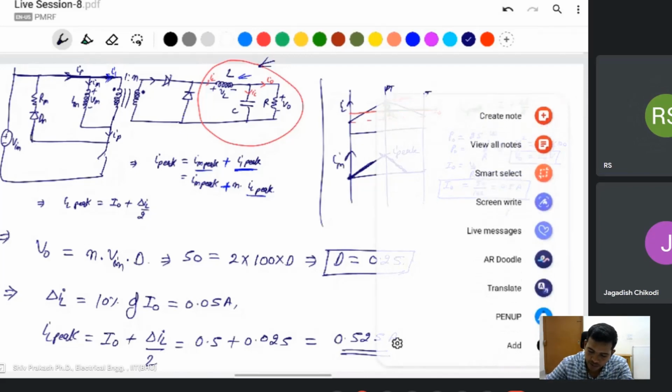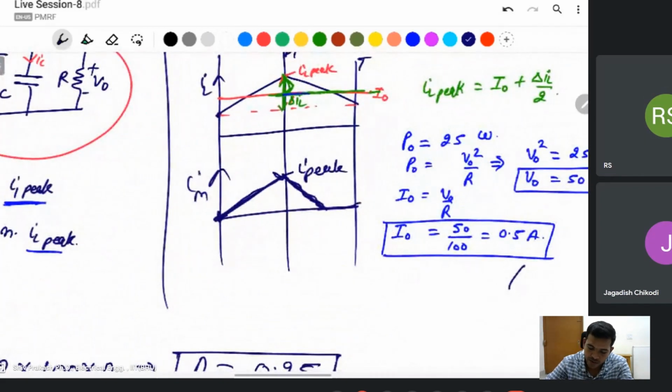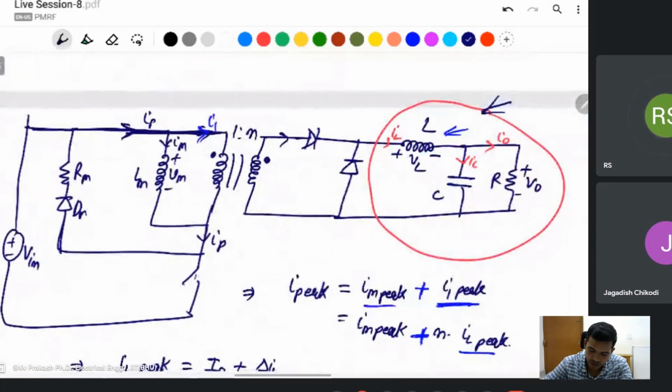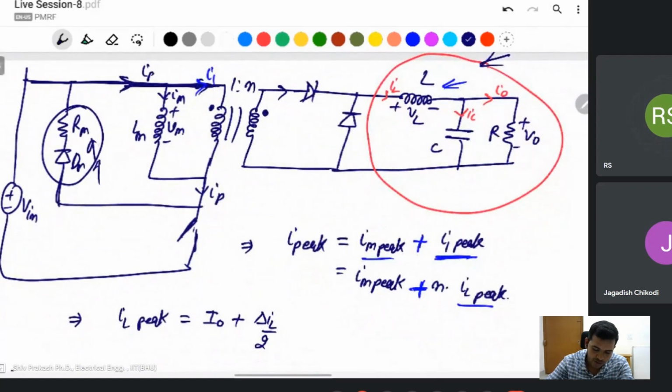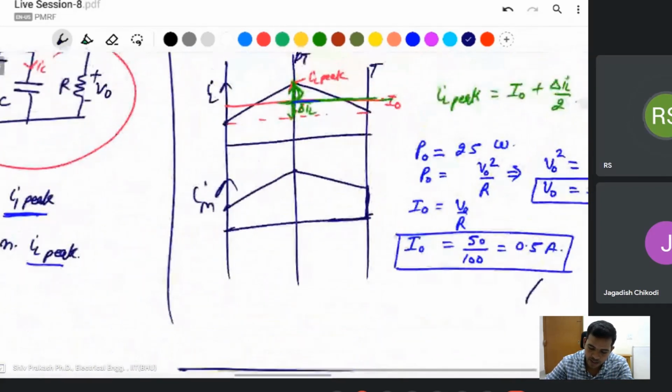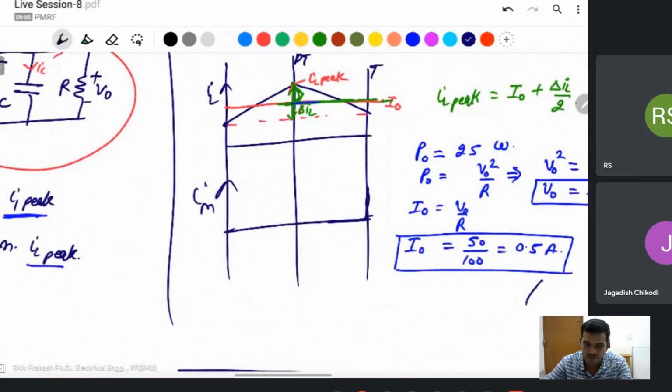I think that in a forward converter, IM is not in continuous conduction because of the switching present here. If you take it like this, it will not suddenly go to zero. Switching is on and off. If this path is not present, the energy is all dissipated in the resistance. But in normal cases, the magnetizing inductance of a forward converter will be in discontinuous conduction mode only.